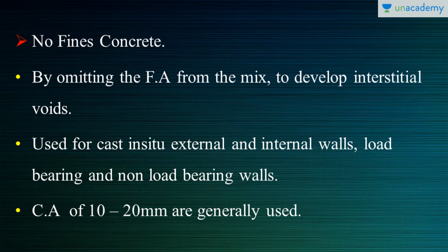The coarse aggregate size varies from 10 to 20 mm. So this is the coarse aggregate range they usually prefer for the no fines concrete. And as the name says, there are no fines in it, which means that almost all the fine aggregates are discarded in this.